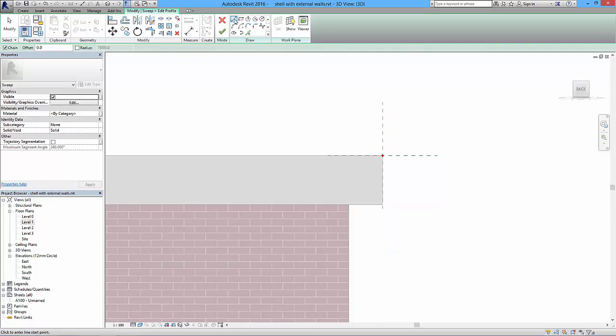So if I choose the line tool, now what I'm going to do is draw outside of this, because the bit outside is irrelevant. It's when it cuts in to this is where we'll have our edge of the roof. So if we wanted to extend the roof a little bit more, then we could do that. But if I just say I want my roof to come up and across and up, and then maybe slope up a bit, then have a little nib at that point, then I can come up there.